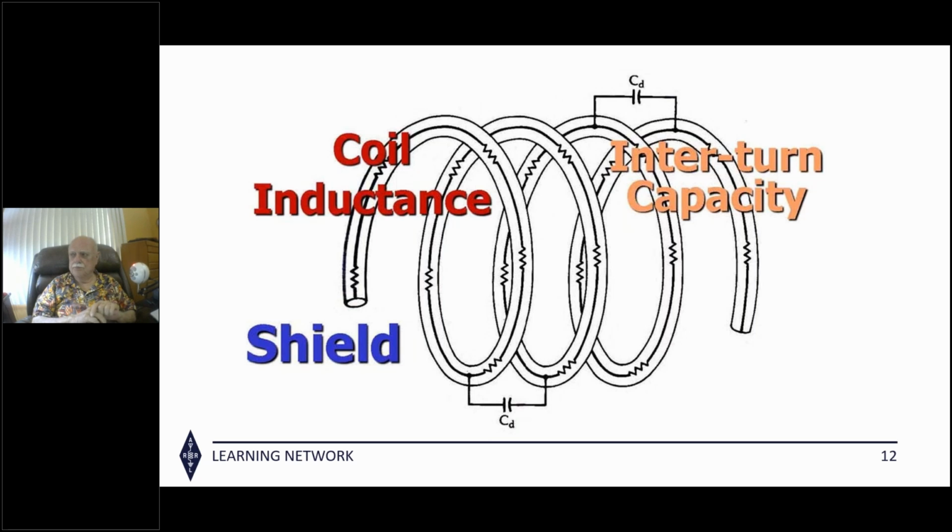And I have read from some sources that an OCF dipole with a 4-to-1 Balun at the feed point can still exhibit common mode current in the shack and therefore need a 1-to-1 or choke at the transceiver. Your thoughts on that? Well, that's absolutely correct. I love off-center fed dipoles or off-center fed antennas. In fact, I've built several of them. Had a wonderful one up at my mountain cabin that I used to have.